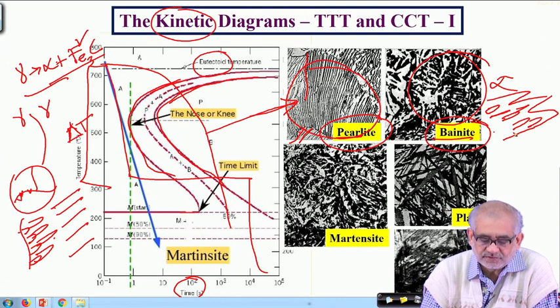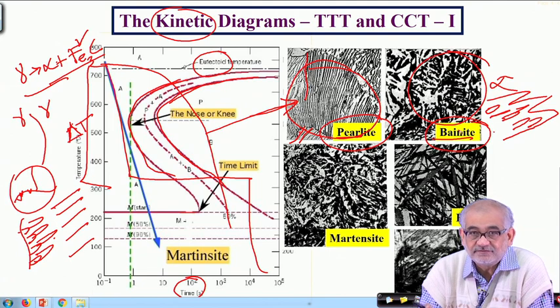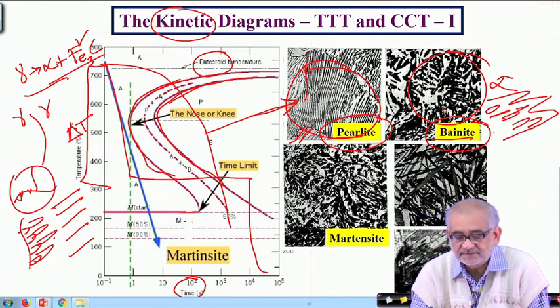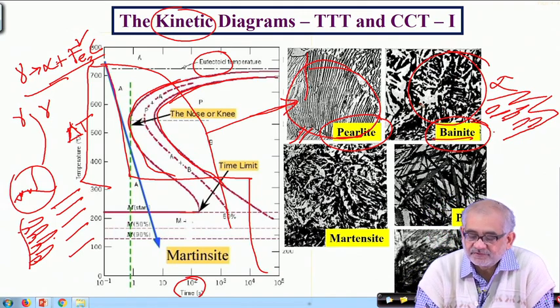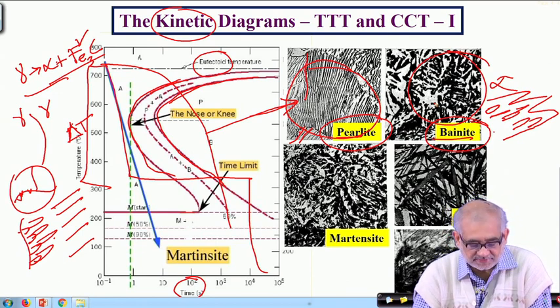So what is important for us to know is that if the microstructure changes from such pure lamellar alternate sequence of ferrite cementite to a situation where we have broad leaf or sheaf kind of a structure of ferrite within which cementite is embedded, we end up getting fairly different kind of properties. In fact, we'll come to that in a minute.